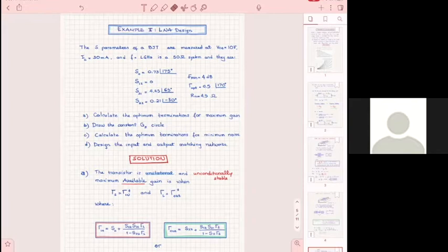What do I give you here? I give you a BJT that has been measured. Usually we always give the bias, even if there is nothing for you to do about the bias, all right? So we always give it because that's the right reference. And then they give you the frequency, which is important, and the reference impedance of the system. It's always 50 ohms.